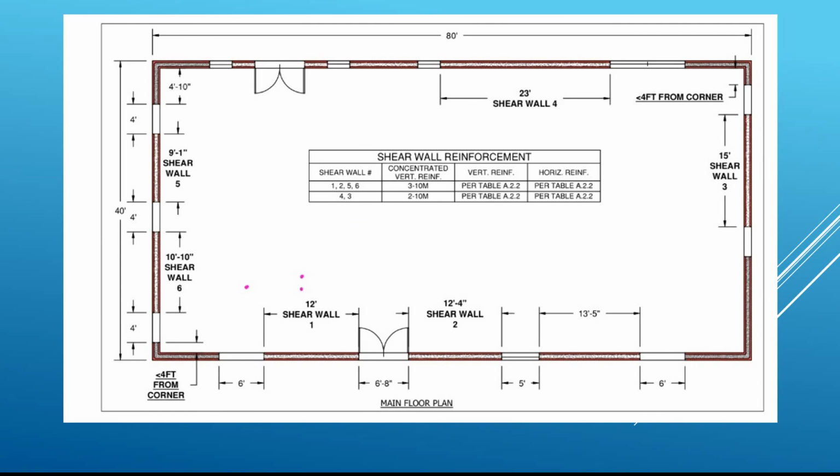But you need to look at that, and that's all driven by whether you've got an opening above grade that's closer to 4 feet, or you've got a walkout or something when it leaves the Part 9 requirements. Then you're going to end up with shear walls. I hope this helps you out.